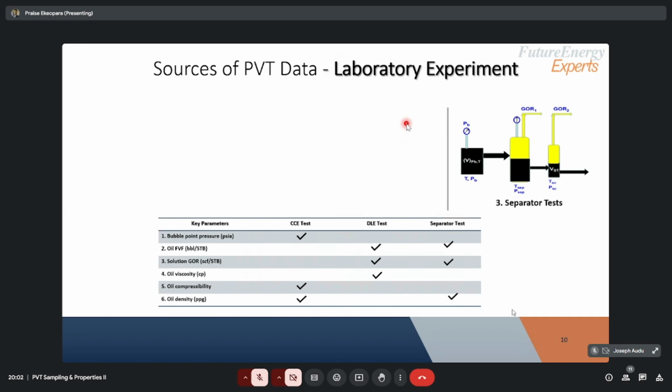Okay, so RS and BO try to measure a change of something at reservoir to that at standard condition. RS is telling us the volume of gas dissolved in oil, right? Then BO is telling us the volume of oil at reservoir to that at the standard condition. You now notice that the higher their values, the less amount we are going to make at the surface, and that's not the whole idea.